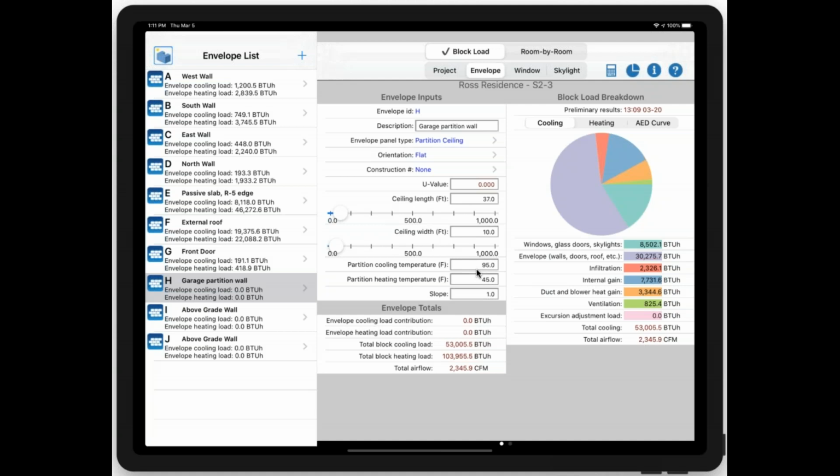If you look at your standard rooftop unit, say a York rooftop unit or even a York split system, usually they have a set cooling and heating capacity. For your typical home, if you have, say, a 5-ton cooling unit, you're going to maybe have 40 to 50,000 BTU per hour of heating. That's just typical. So you may want to look at some equipment selection for York or Lennox units and see what they say.